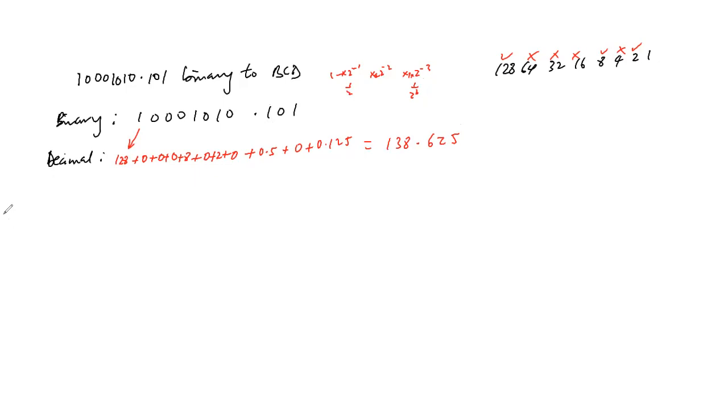And then from this, we will come back to BCD, right? So this now is the same as 1, that's 0001. Then 3, it means these 2 bits are turned on, 0011, for the 8421 BCD code, right?